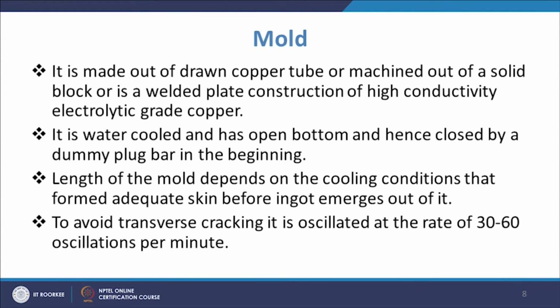So initially we close it with a dummy plug bar, and then water will be coming and flowing, and during that process that water will be absorbing the heat which will be released by the liquid metal in the mold. That is why you will have the change in the temperature of the incoming water and the outgoing water, because that water will be taking that heat which is being released by the mold.